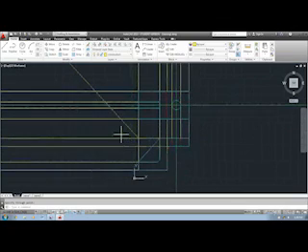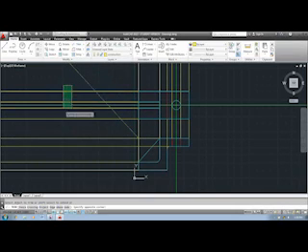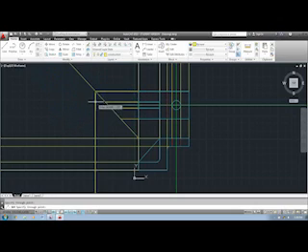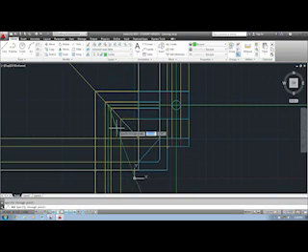Okay. Now the reason why I drew this 45-degree line, I'm going to end up trimming everything off this side here. So I'm going to have this be my trim, and then these be trimmed. So that way, they all kind of end there. I'm going to pull up the ray command again. Every point that these hit, draw the necessary rays. And come to the center. Oops. Draw a ray right there.